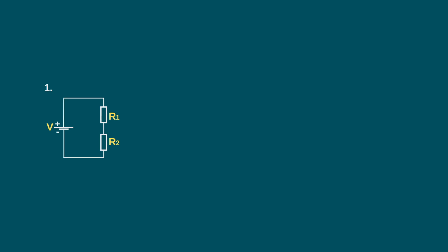Hello. Through a few examples we will get to know the application of series connection in various electronic circuits. The first example is standard. 2 resistors and power supply. It is necessary to calculate the total resistance Rx, current I, and voltages V1 and V2.